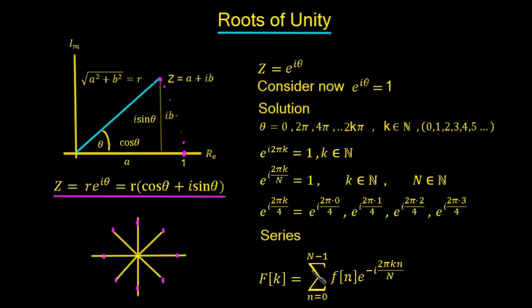So don't get lost in this. This is just another way of looking at our surface, which is our e to the i omega t, splitting it along the frequency axis, so making it discrete along the frequency axis, making it discrete along the time axis, multiplying by our time function f of nt, and then summing up the values to get our function of frequency.